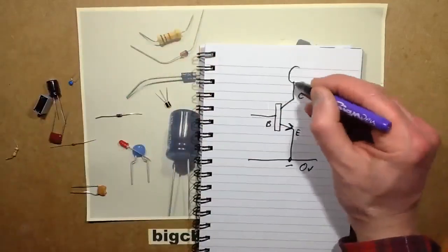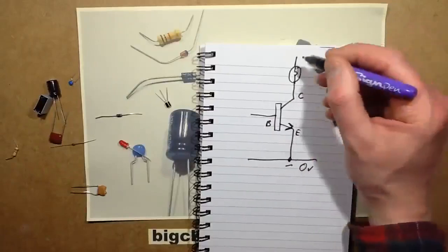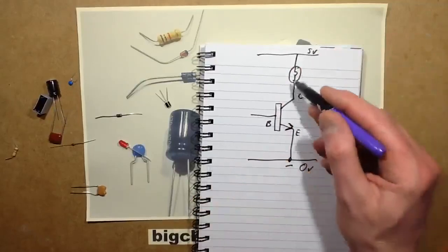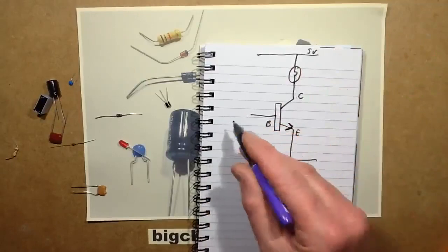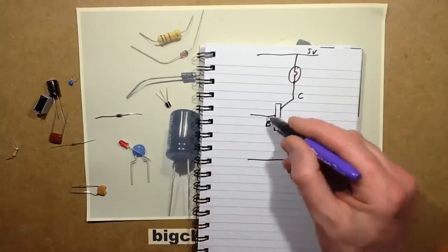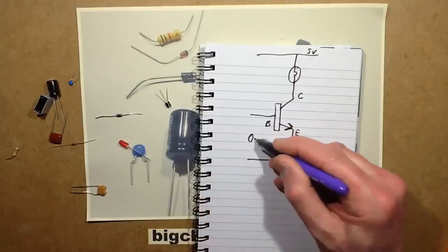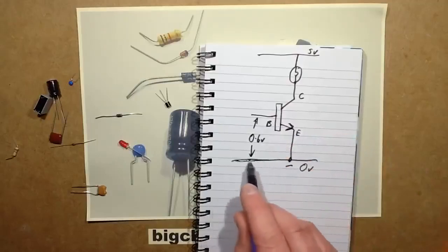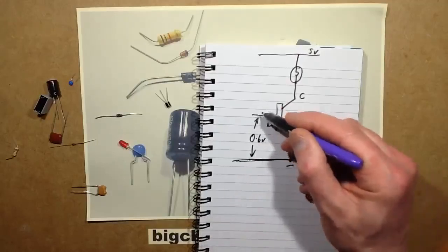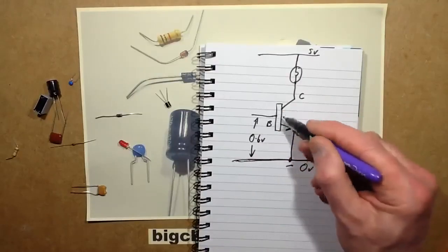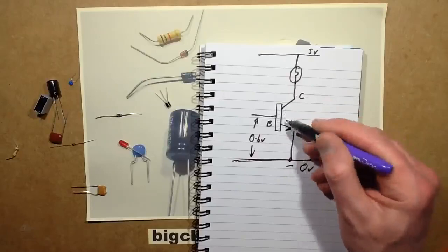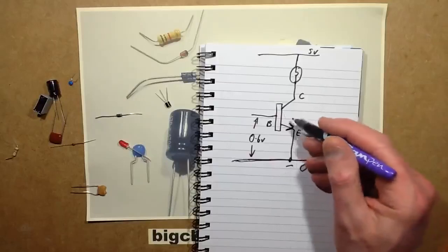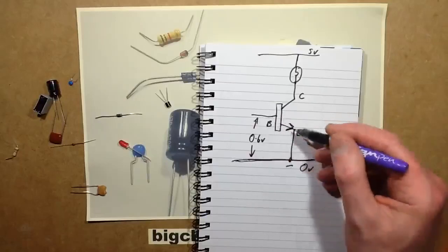Supposing, for instance, you had a small tungsten lamp and you had, say, a 5 volt supply. If you wanted to turn the lamp on and off, but you only had very limited current available, you can use a transistor, and as soon as you exceed about 0.6 volts, because it's silicon again, that's the standard silicon junction voltage, above the ground rail, the 0 volts, and a modest current. A transistor typically has a value called a gain. It's got a voltage rating, a gain rating, a power dissipation rating. There are lots of other ratings, but let's keep it simple, because in most instances when you're using a transistor, it's going to be an NPN that's going to be like this.